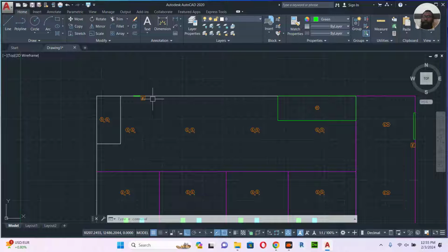So as per that, the government has some standard, like every 30 feet there should be a smoke detector, not the smoke, the fire alarm system breaking glass. We call this breaking glass, otherwise we can call this a manual call point, and there are too many names for this. So there is a rule like that. Same way the exit light, everything you can find in the life and safety drawing.